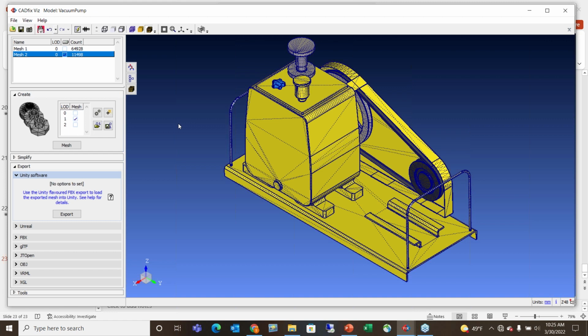Great, thank you. The next one is, can this program remove features like holes and protrusions from the model? Well, it does remove them from the mesh. The way the program ultimately works underneath is that you're never exporting CAD geometry in the end anyway. So instead of really removing things, what we're actually doing is suppressing features when meshed.